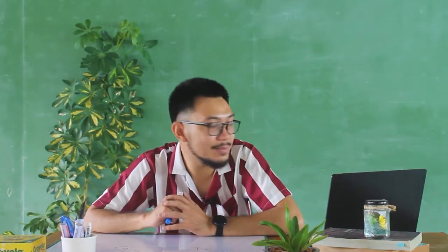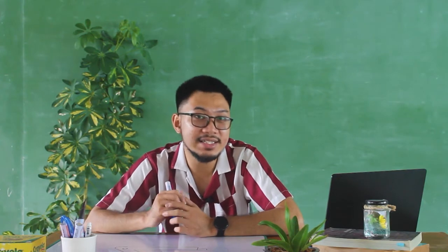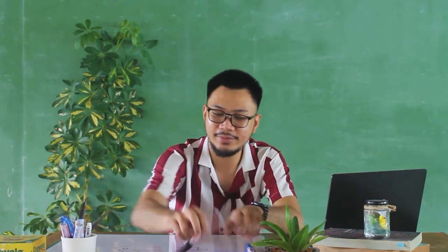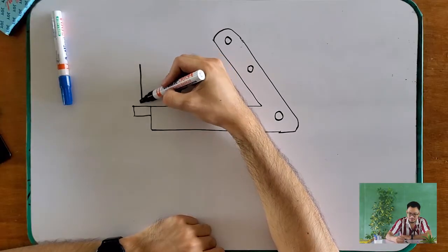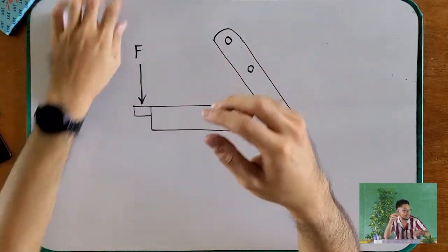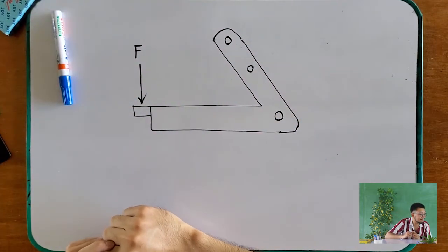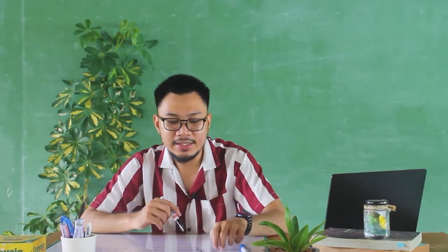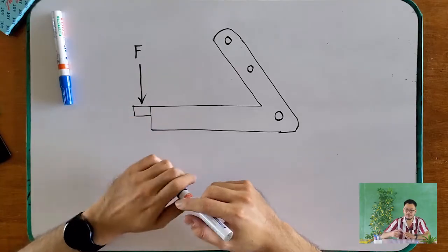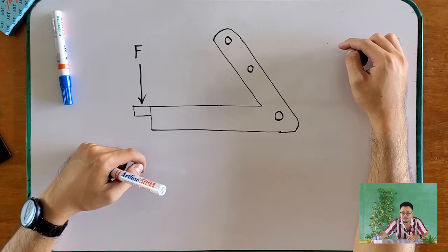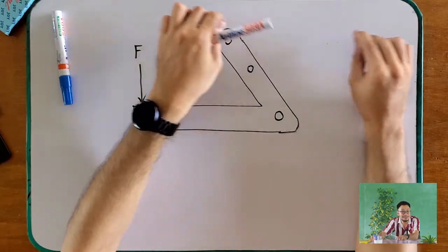So first, at your point B, you have your weightless link. And now what is the direction of our weightless link? Since you are applying a force on our lever, and it is said that the force on our link is 20 pounds. So, when we put a force on our link, what will happen to it? Our link will be pulled.